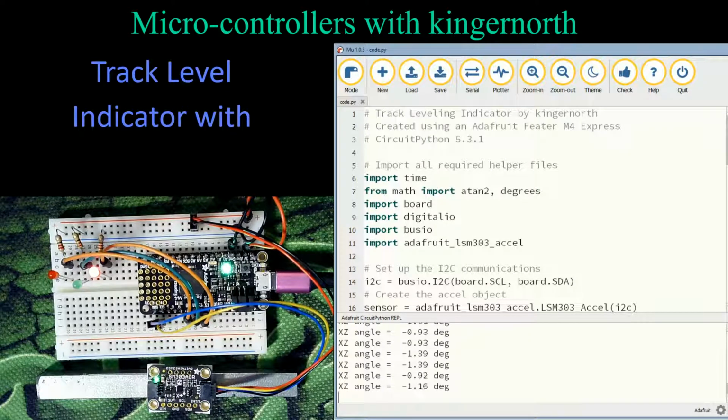Oh, you gotta love I squared C. It depends really well. So that's what happens when I was doing my drawing, because I didn't actually have it hooked up to the board. So looking at my drawing, you just gotta make sure you hook up SCL and SDA to the proper pins. It's really picky that way. Imagine that. Okay, so there we go. We're up and running though.